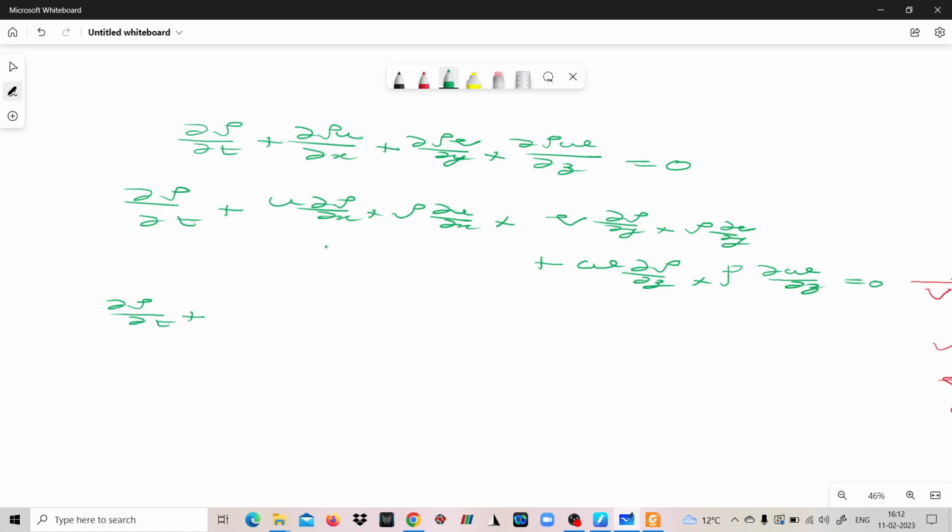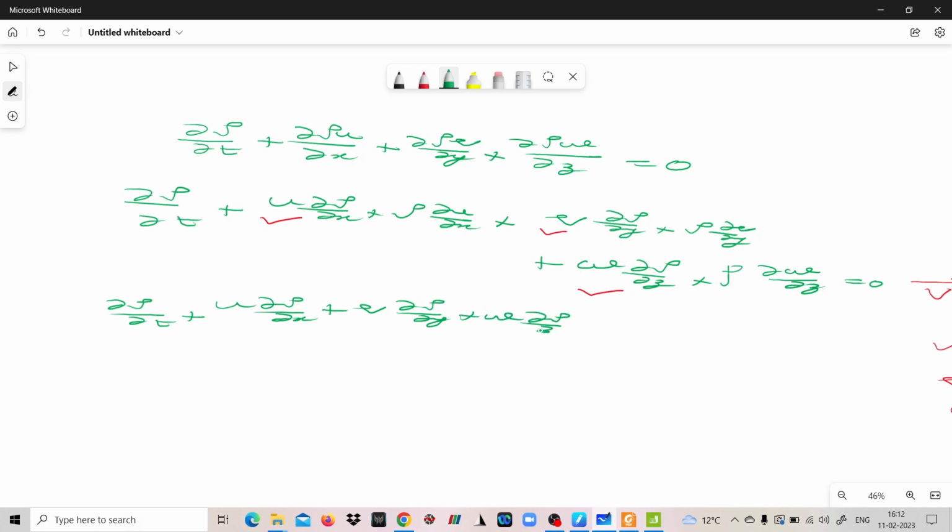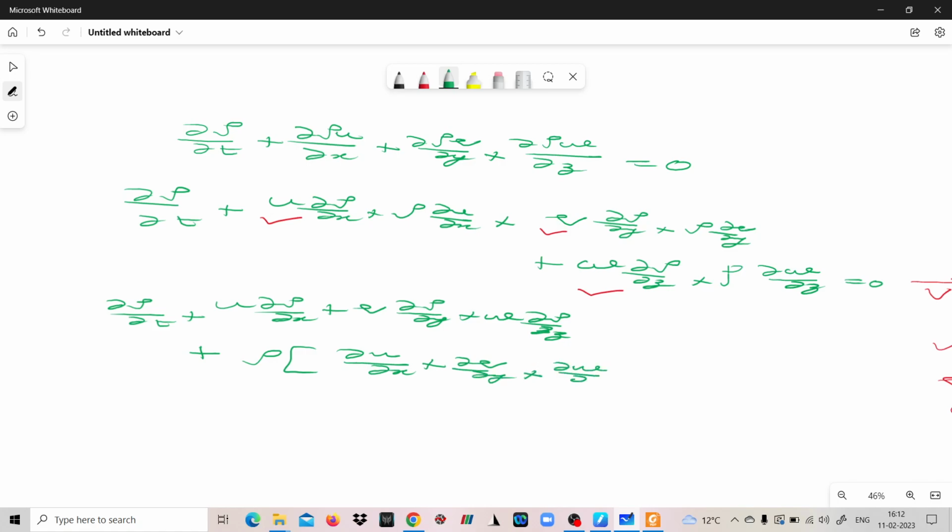Now if we club together these terms, we can write this as u del rho by del x plus v del rho by del y plus w del rho by del z plus rho times del u by del x plus del v by del y plus del w by del z is equal to 0.